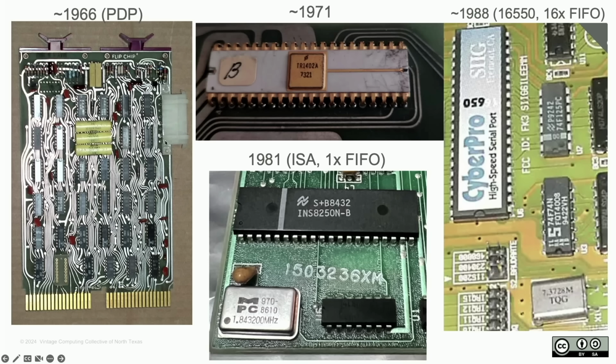Finally got that done. Then formally, one of the earliest UARTs, a lot of us think about the 8250 on the IBM PC, but really a decade earlier was this 1402, I believe from Texas Instruments. Pretty sure we'll see this in the ADM-3A. All right. And then around when the PS/2 came out, this faster 16-byte buffer came out and became popular, the 16550. So that's kind of the history of UARTs that are available out there.